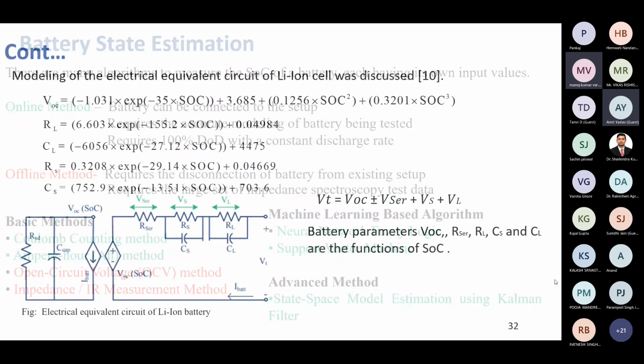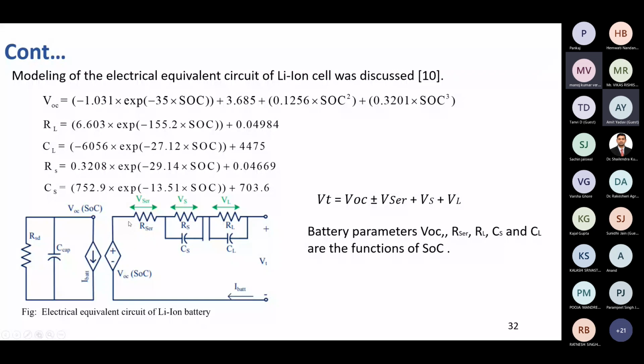With this discussion of the battery, we have modeled a complete equivalent circuit that considers our battery characteristics. I have shown the dynamic and non-dynamic, resistive model. We have a resistance, and we have also connected the RC branch and the internal capacity of the battery, to make it an exact model.